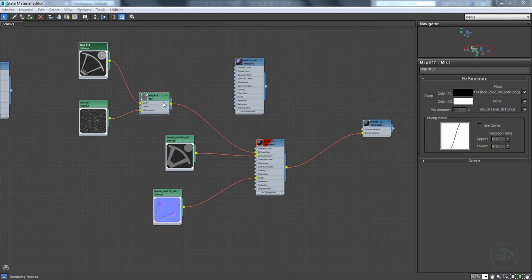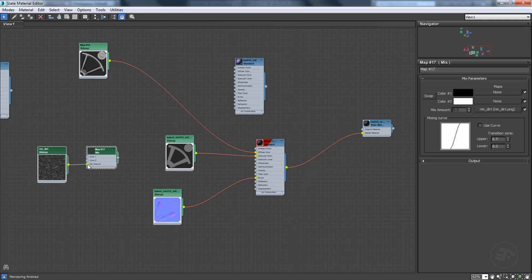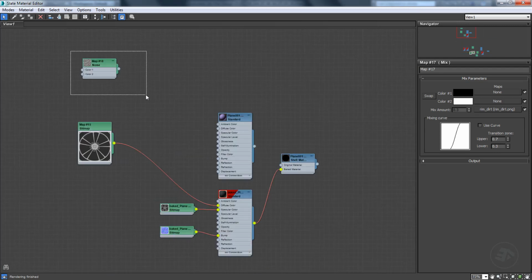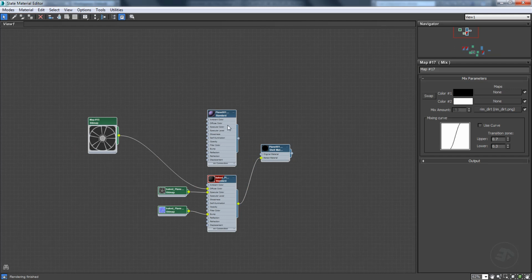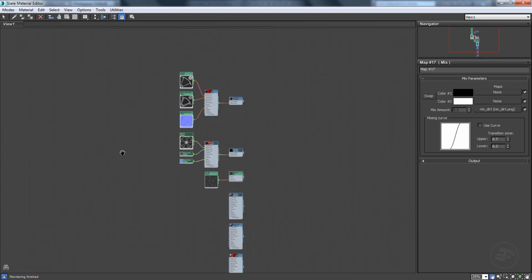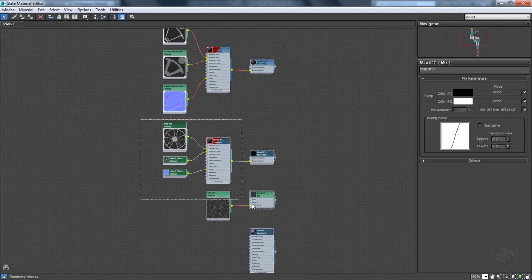When you start adding more materials and maps to your project, you will need to organize those materials to ease the visual recalling. Unfortunately, grouping nodes in the State Material Editor is not yet available in 3ds Max, even with the newest version. When deleting materials or maps from the State Material Editor viewport, if those materials or maps are not assigned to any object, they will be gone for good.